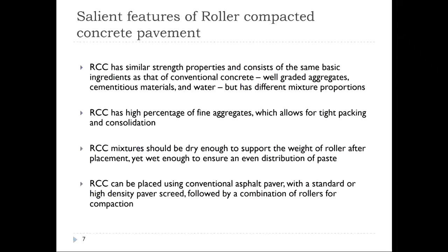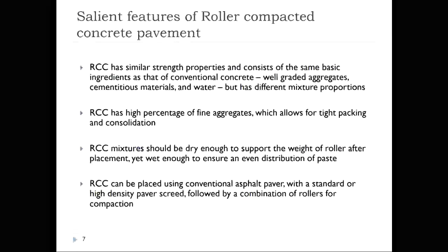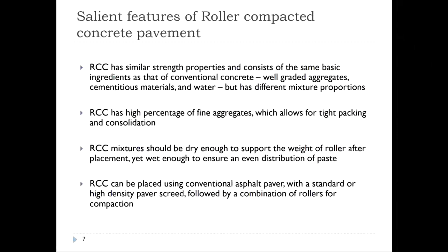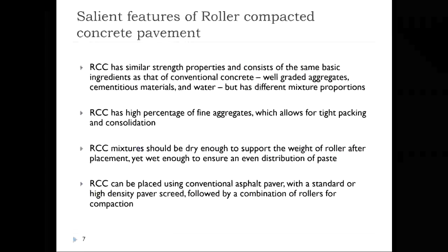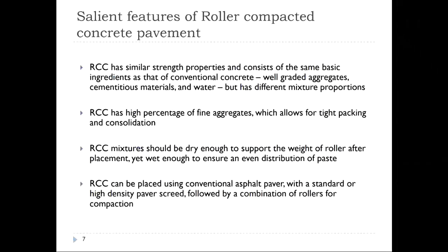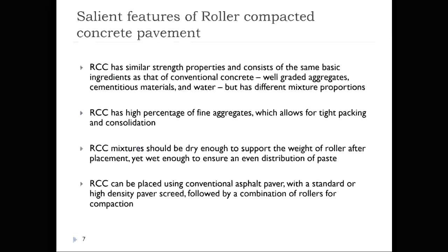Now, in the case of a conventional concrete, the aggregate gradation plays a less important role when compared to the stiffness of the mastic. In conventional concrete, it is basically the CSH compounds, the calcium silicate hydrate, which are formed. Basically, these are the hydration compounds. They are much more predominant in terms of carrying load than the aggregate gradation. But in the case of roller compacted concrete, our aggregate gradation plays a significant role in the load carrying